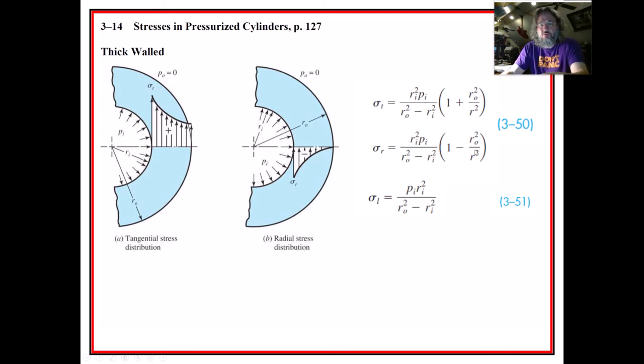And if you were to put these values in, you'll see that we're using Ri, Ro, and if you look closely, one of the R's doesn't have a subscript. That's the actual radial position from the center of the thing. So this equation is really giving you the distribution of the stress, and it's really starting from Ri, right? It doesn't make any sense for anything less than Ri. So starting at Ri, this equation is showing that curve of a distribution. Does that make sense? Hopefully.